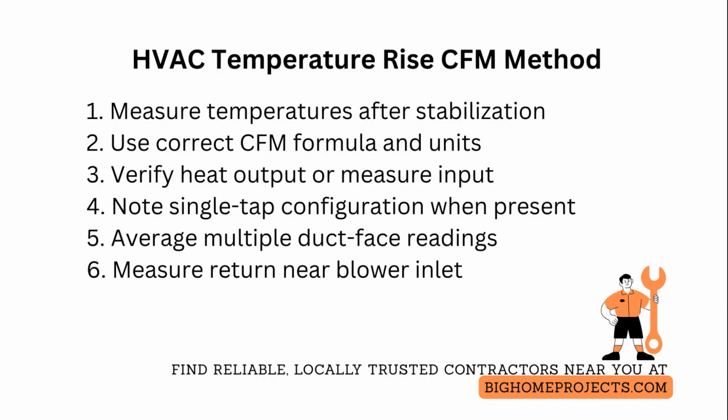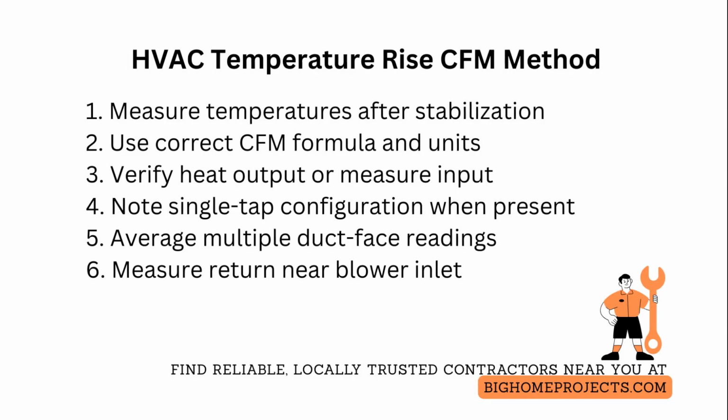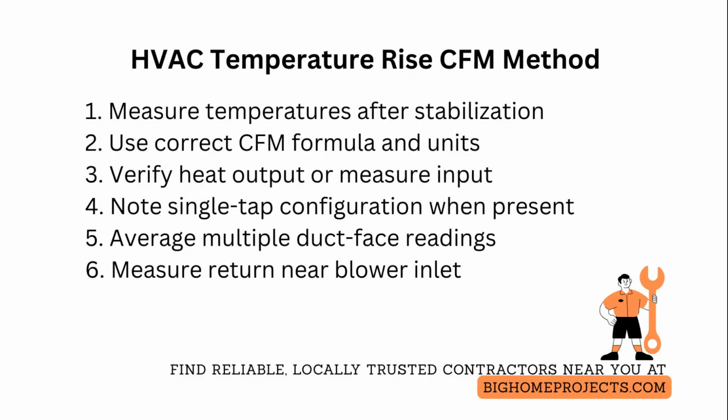If you do not have direct BTU per hour from the furnace, measure electrical current and voltage for electric heat, or read the rated input on the nameplate and correct for blower off cycle time. Document whether ratings are steady state or nameplate values.